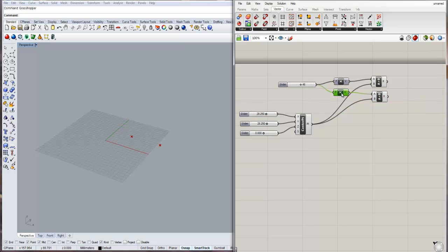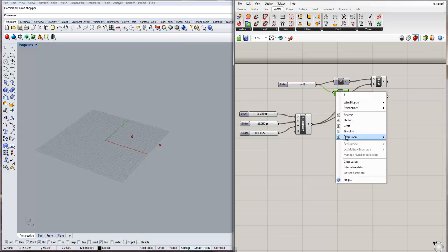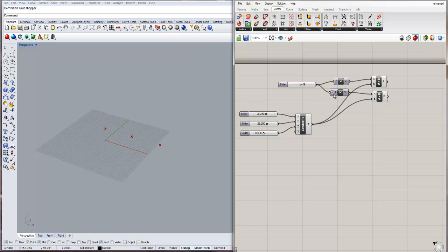In order to make this as the opposite point, we'll click on this F, right click on F, and you'll see expression. I'll put here -f and commit changes. So which means that if this number is 46, this f will actually use negative value of this slider bar. So that's why it's going opposite direction.